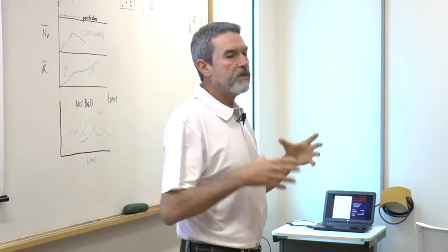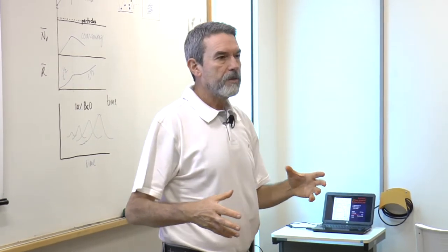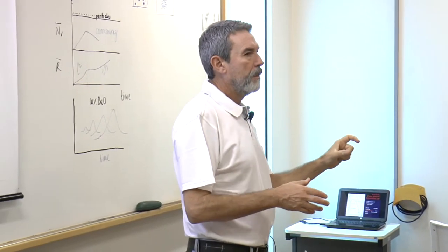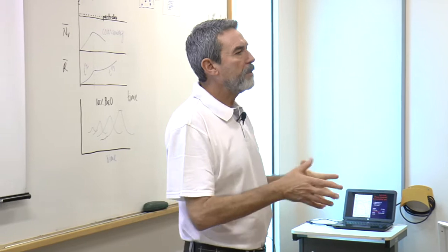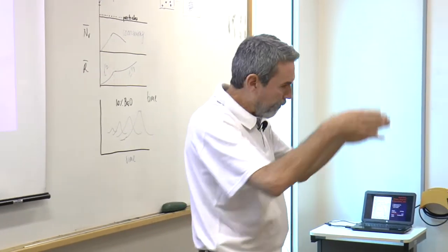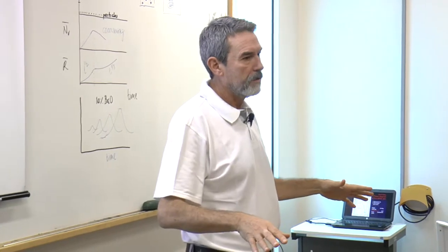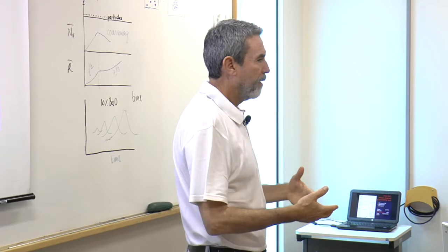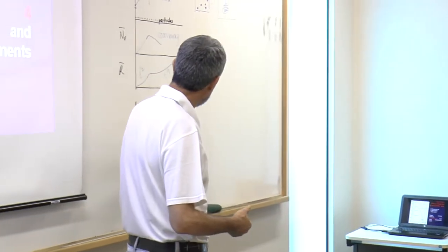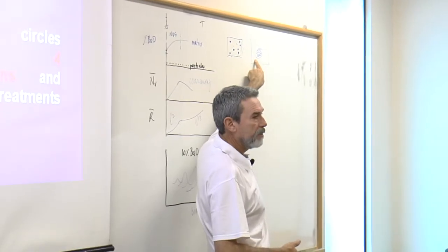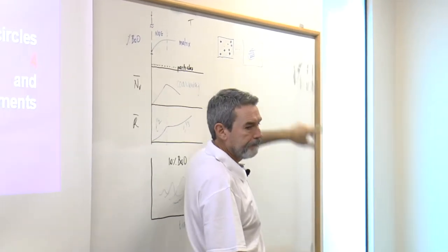The major difference is the beginning. Compositions inside the binodal boundary separate by nucleation growth. Inside the spinodal boundary, they separate by spinodal decomposition. But in the end, the coarsening process is the same. Even this one here, in the very end, should finish as this one here.